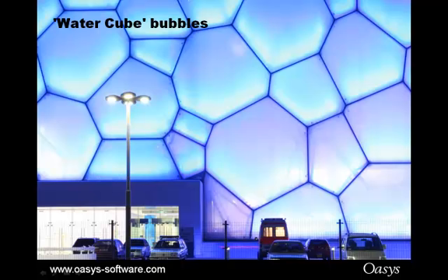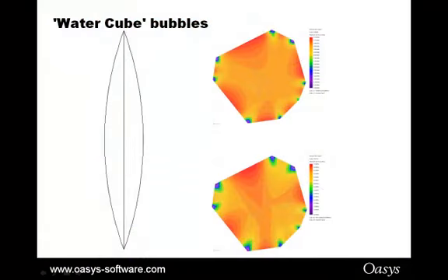And because the larger panels, to get them to the required pressure, were going to be yielding too much, they had to preform the ETFE foil, because you can just about make out the strips in the foil, and they used GSA to find the initial shape, pressurize them up, and then you can use the wind and snow loads and so on on these claddings.